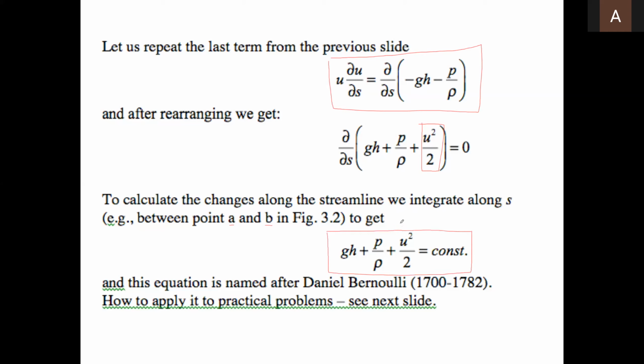I don't like to call it energy. I just call it Bernoulli's equation. It says that the body force or gravitational potential, plus P over rho, plus the velocity squared over 2, is equal to a constant. Any mechanical engineers, you use that as enthalpy, by the way. So you're probably not mentioning Bernoulli, but that's the same thing, because that would be kinetic energy, and that would be energy to pressure.